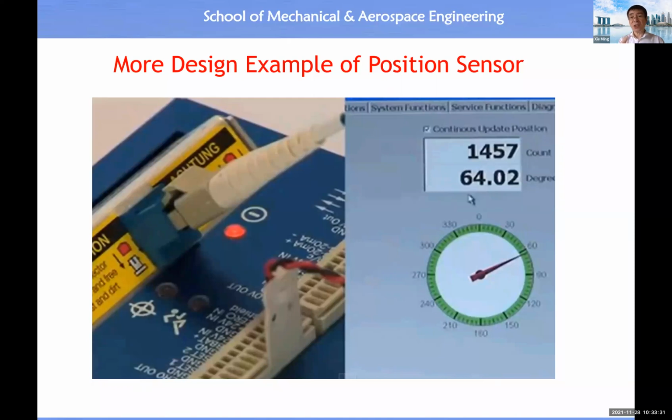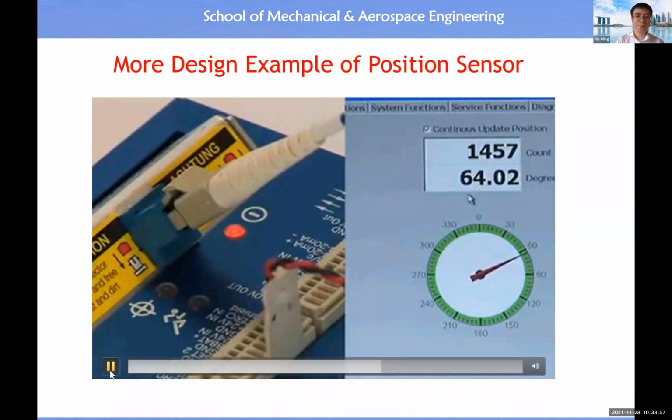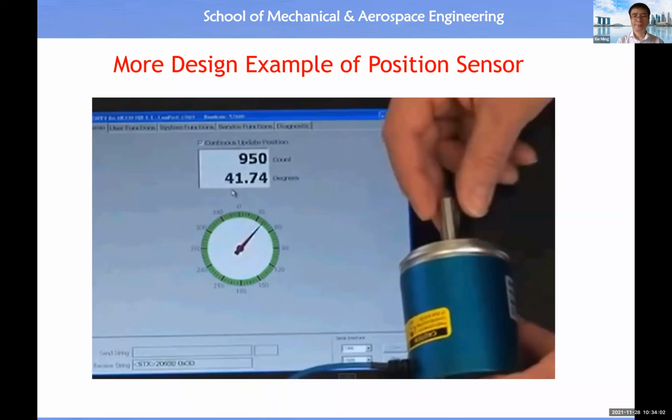Okay, it would increase the cost a little bit, and who knows, maybe one day the cost of the absolute encoder will drop. Once you incorporate an absolute encoder, then you do not need to do the homing because you can turn off your robot and turn on your robot immediately. You know the initial angular position for each joint. All right, so this is something for you to know. The sensor will always know its exact position, whether the shaft is stationary or rotating.